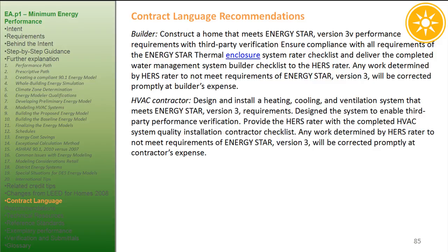Contract language recommendations. Builder, construct a home that meets Energy Star, version 3 performance requirements with third-party verification. Ensure compliance with all requirements of the Energy Star thermal enclosure system rater checklist and deliver the completed water management system builder checklist to the HERS rater. Any work determined by the HERS rater to not meet requirements of Energy Star, version 3, will be corrected promptly at builder's expense.